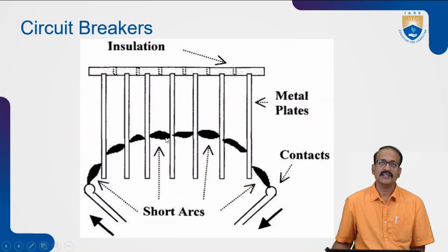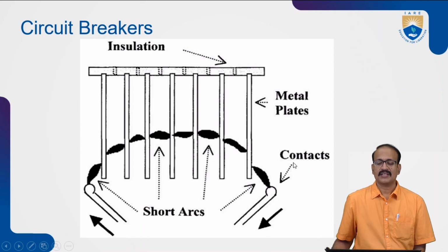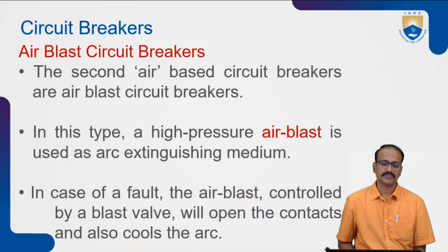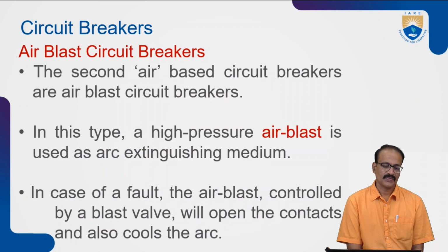This is the representation here. These are the contacts, this is the insulation, and these are the series of plates. You can observe this is the arc. These plates have divided this arc into smaller arcs. This is the technique we are using here for extinguishing the arc.